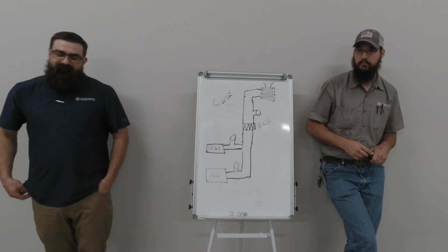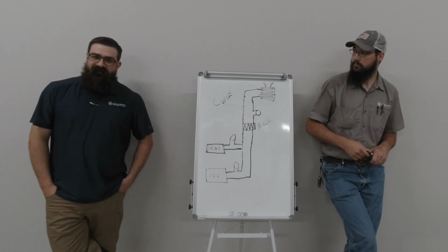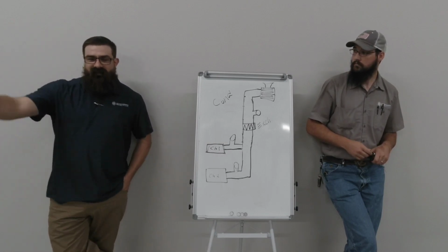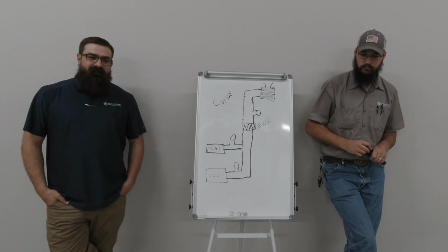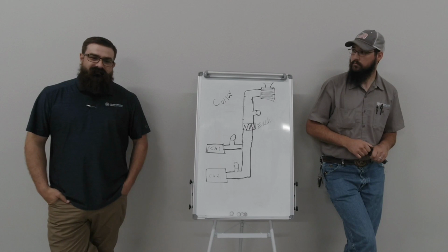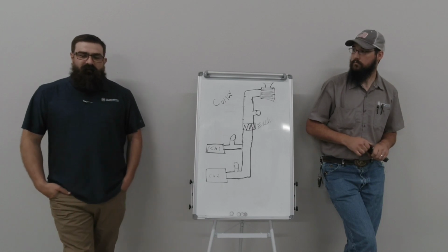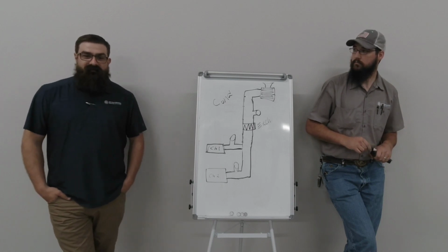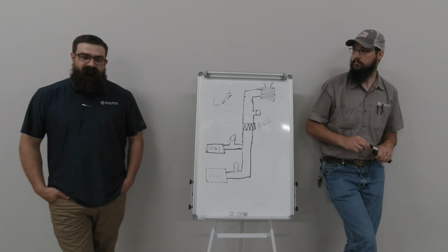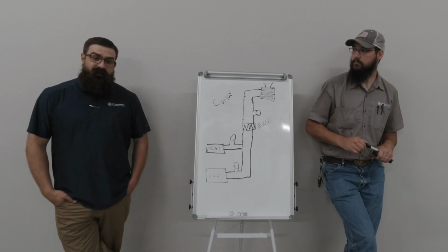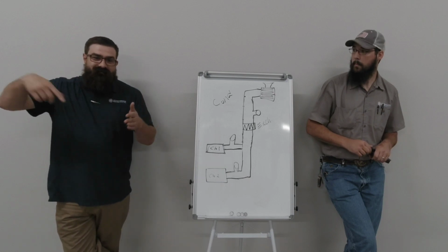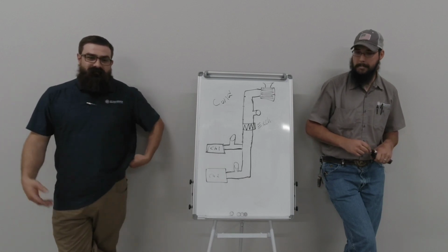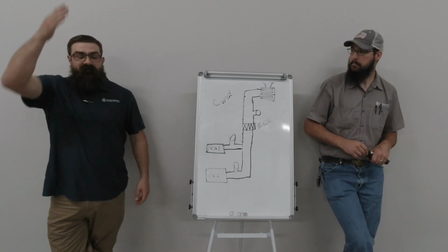Yeah. The random fan power box placement is, oh, here's a TI, let's just slap this one in right here. So, yeah, that's usually nothing to do with proper design. Any TIs are always going to be random. They just need a place to put it, so they put it somewhere. And even coming from engineers, it can be that way, because they're working in this much space and they've got to fit an extra box to cover the load of that space. So they just find the open spot on the ductwork.